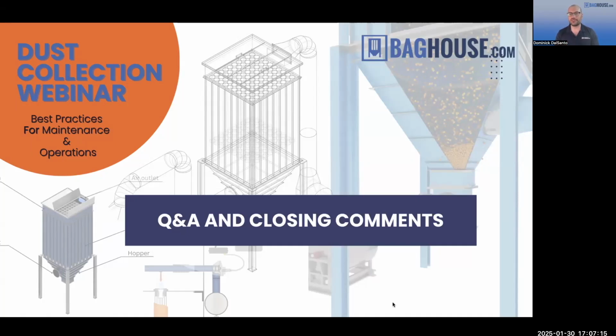So in a normal system, when we size it, we size the baghouse so that while you're running at full capacity, however much dust is coming into the collector can be removed by the cleaning system without having to shut down, right? So let's say 1,000 pounds per hour comes in. We size the system so that it can effectively remove 1,000 pounds per hour or a little more without having to shut the system down, without having to turn the fan off.